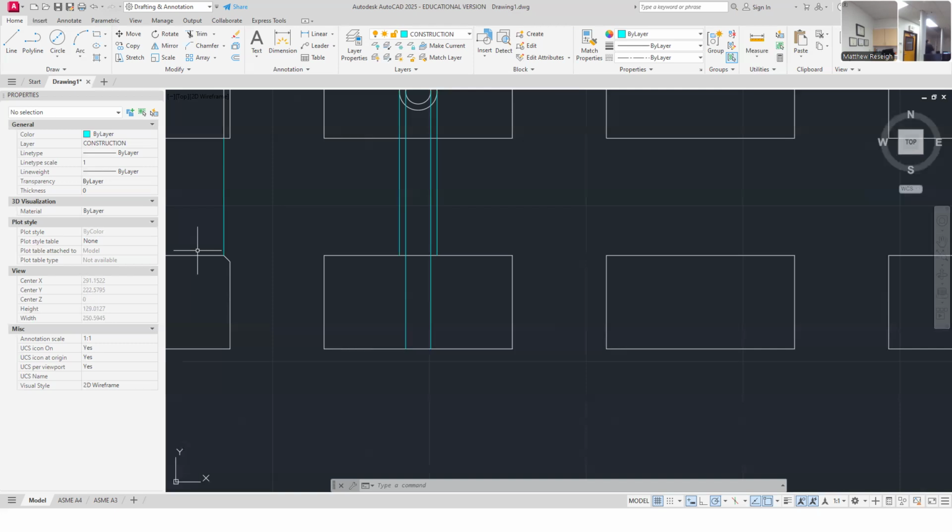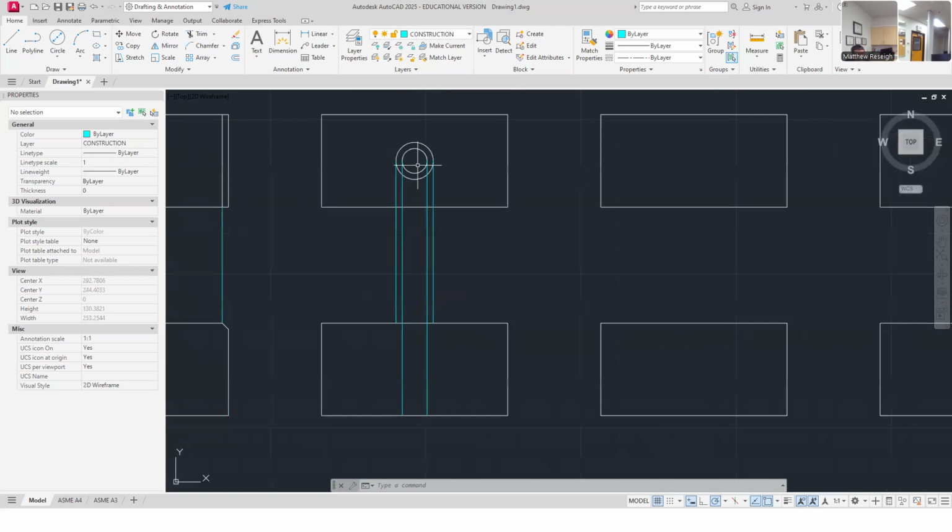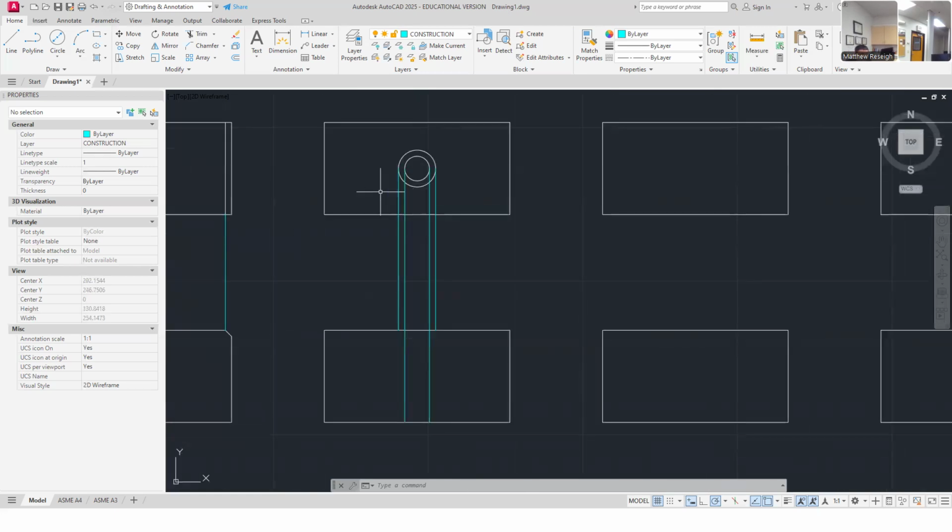But we like to sink these generally. Flathead machine screws always have these tapers or these angled heads, and I've never seen them not get sunk into the material. So there's a different type of tooling that cuts that into what we're drawing, and we are drawing what will accept these bolts. There's more to these drawings than this, but these initial drawings are just where that bolt might go. Of course, when you're drawing stuff like this that's going to accept bolts, there's tolerances involved. There's threads that have to be cut in some instances, but this is a common flathead machine screw.